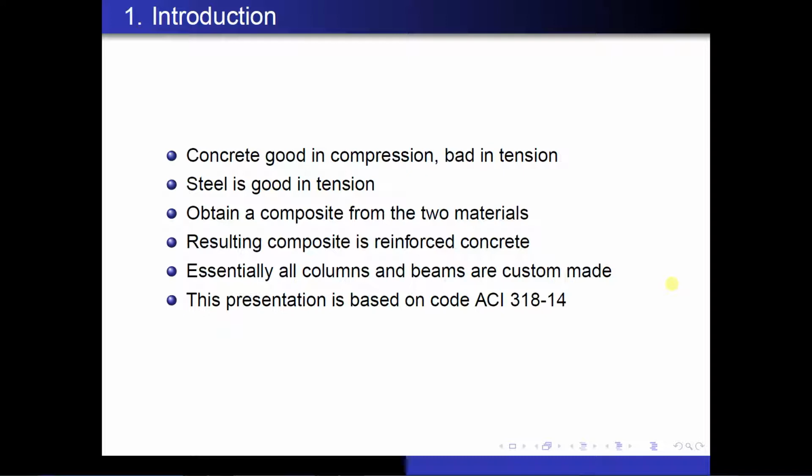So first off, it's important to realize that concrete is good in compression, but is very bad in tension. And so when you are designing a structure with concrete, you will add reinforcing steel in those locations of the concrete where it is in tension. By doing that, you will have steel that can take the tension loads where the concrete is not so good at doing that. As a result, you're going to end up with a composite material. This composite material is made up of the concrete and the steel reinforcement.